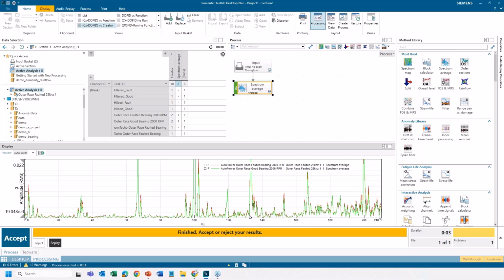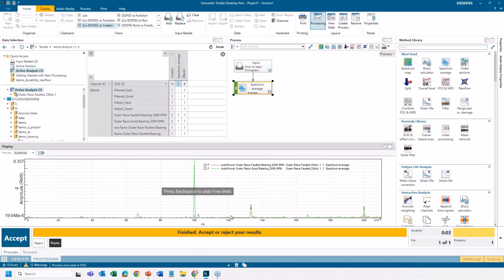Yeah. Not only that, it's buried in there. It's hard to see this fault frequency. There's a lot of other things that are going on in this rotating system, and the vibration from the bearing can be pretty small. Now, I'm going to do something else here.